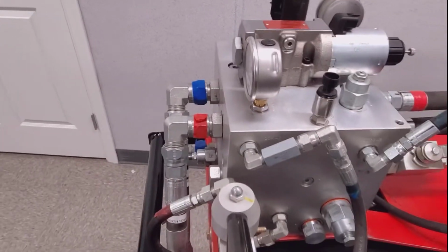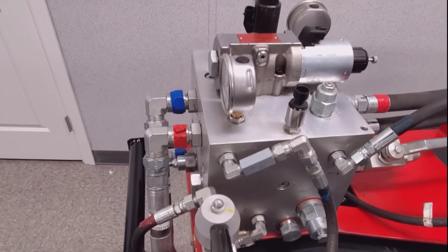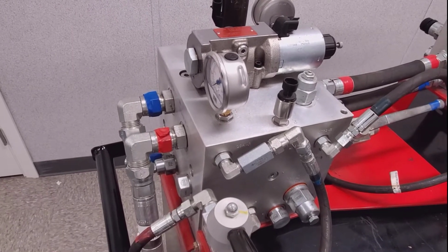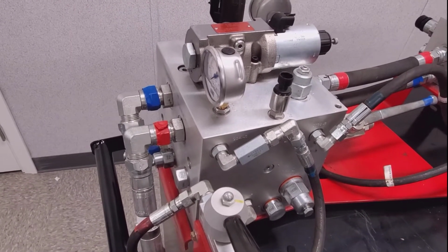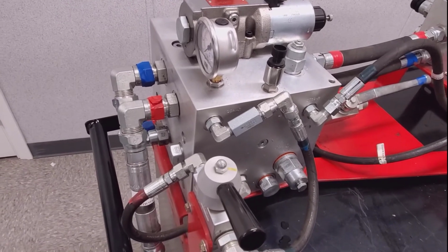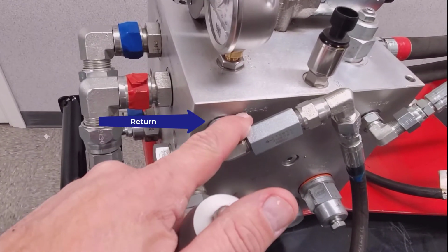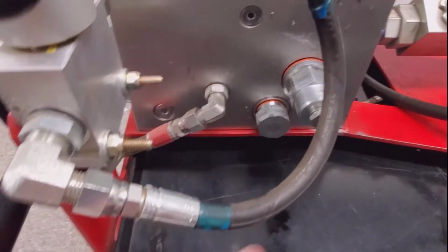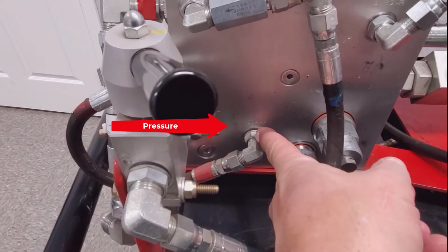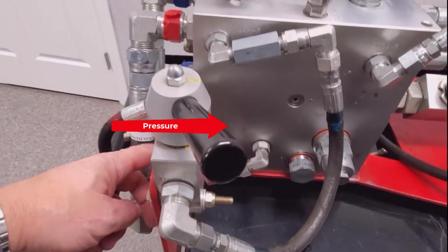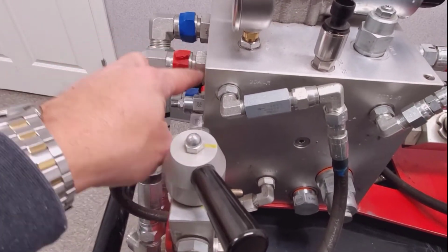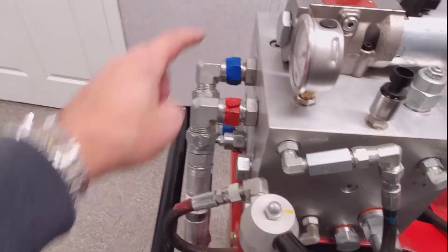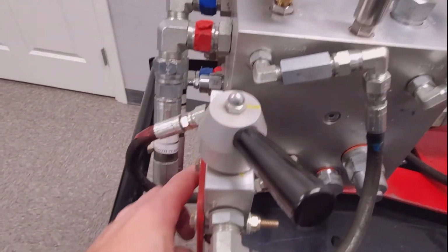Coming off of our valve, if you've got high float hydraulics, a QDA frame is able to lift and lower the frame to adjust seating depth. Or if it had AccuSet, it'd be ported in the same spot. So we have a QDA R, that's return, and a QDA P, that's pressure. So pressure oil is directly ported to the pressure here. We don't go through the control valve, it's directly ported to here, comes in here.